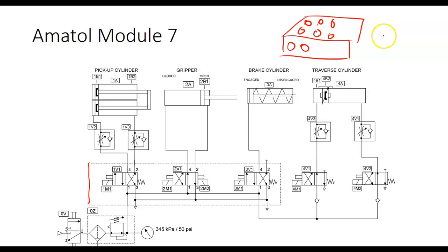Now on the Festo line, the manifold actually runs through the valves. So we have two end pieces, and this is where your pressure and your exhaust will be. And then the valves just sandwich in between the two, which means now I'm not dedicated to buying a manifold that you can mount 4 valves on or 3 valves on or 2 valves on, right? You understand that? Basically, we can sandwich multiple valves between that. But the manifold actually runs through the valves, which is pretty interesting. So you'll see those things have got lines running all over the place.